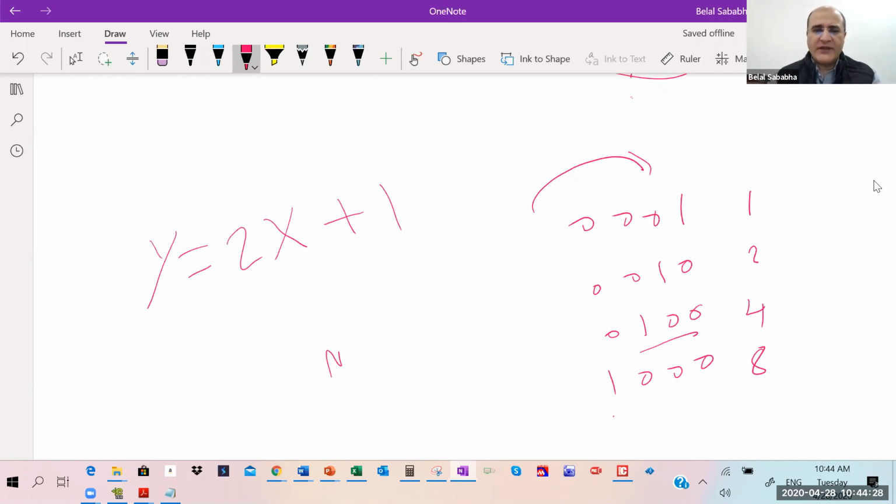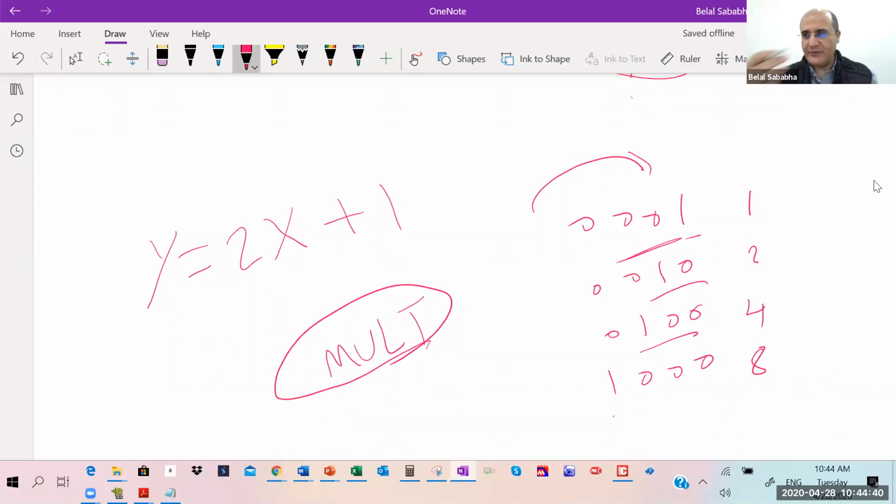To do a multiplication operation? Well, in our microcontroller, we don't have a multiplication instruction, so it's going to be converted. This could be converted to shifts or to multiple repetitive additions. So a shift will be faster.